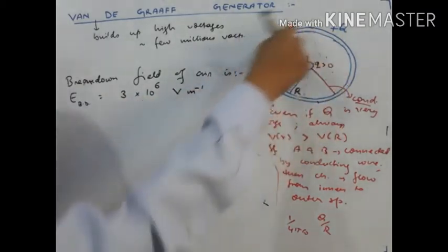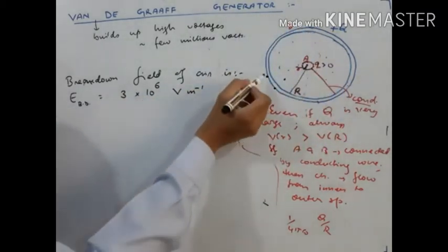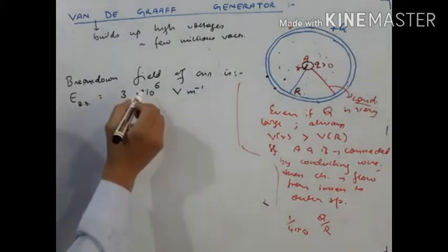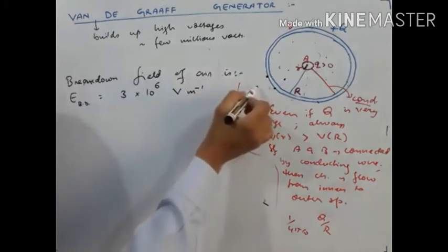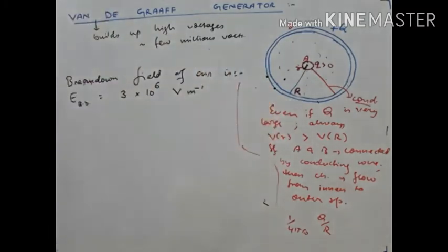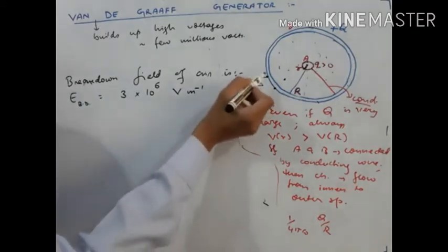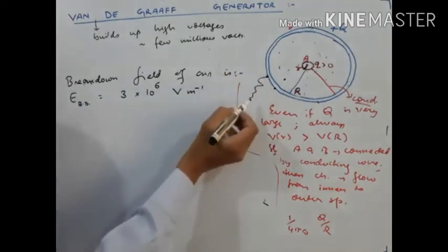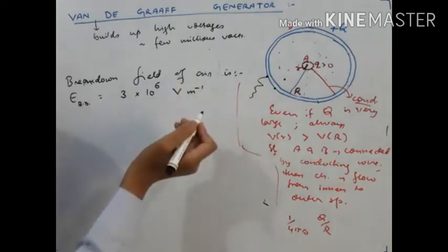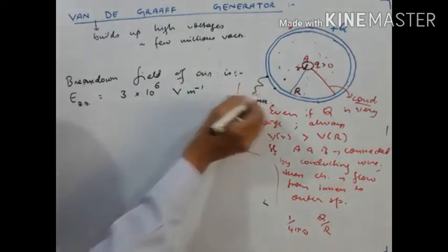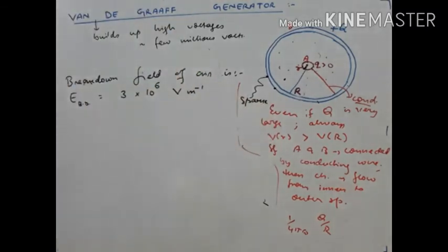If this charge goes on accumulating, there will be one situation where it creates a potential, or an electric field, which reaches this value. Under that circumstance, the air loses its insulating property. That means through air you will have flow of charges. These charges cannot stay as such, they will flow through the air, and that we call discharge. So electric discharge will take place. What you will see is a spark. The discharge will result in a spark, just as you see in case of thunder.